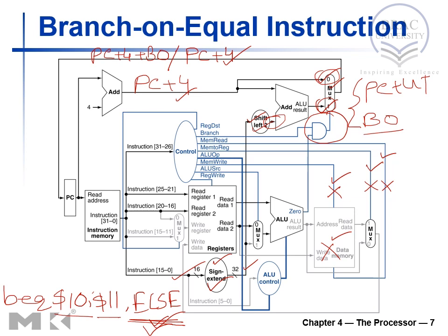And ALU source, this link will select both the links coming out from the register file, since this is register 10 and register 11. So ALU source would select port 0 of the multiplexer. That means this port will be selected, and you already have the value coming from this link. So this is how branch on equal instruction would get executed.